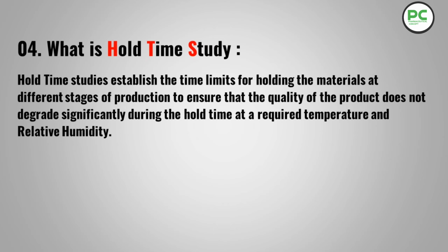What is hold time study? Hold time studies shall establish the time limits for holding the material at different stages of production to ensure that the quality of the product does not degrade significantly during the hold time at the required temperature and relative humidity.